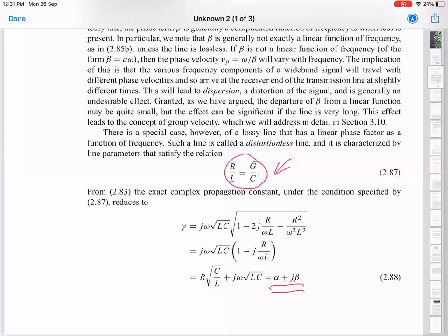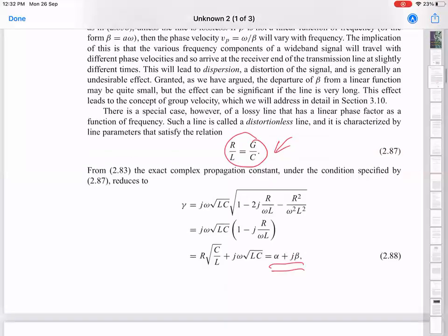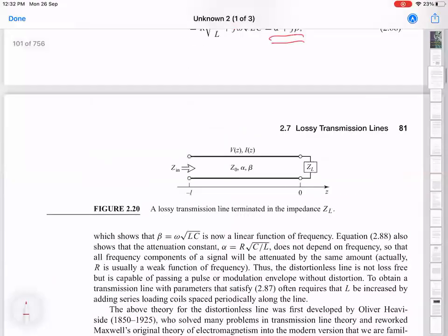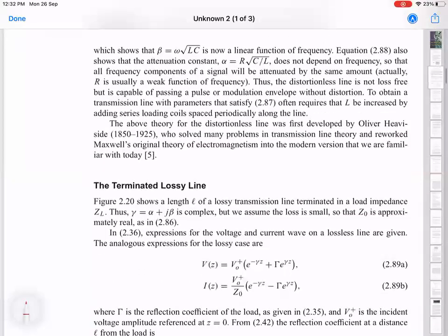Usually in a cryogenic system, the lowest temperature is defined by an equilibrium between how quickly you are removing heat and what the leftover heat influx is. When the two get balanced, that's the temperature at which you stop. So by adding a very good thermal conductor, you're going to make that worse. It will heat up. It will have a higher temperature, which is not going to be acceptable for most situations. Okay, so that's all for this discussion this time.